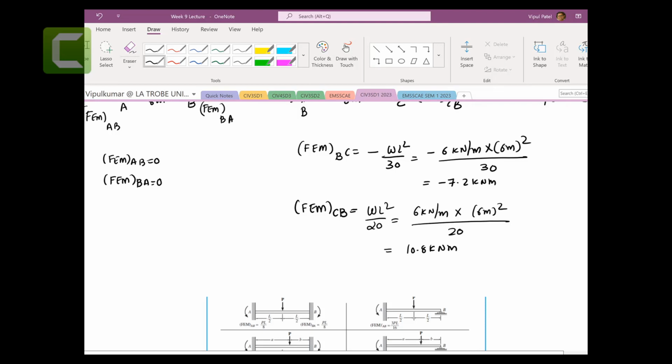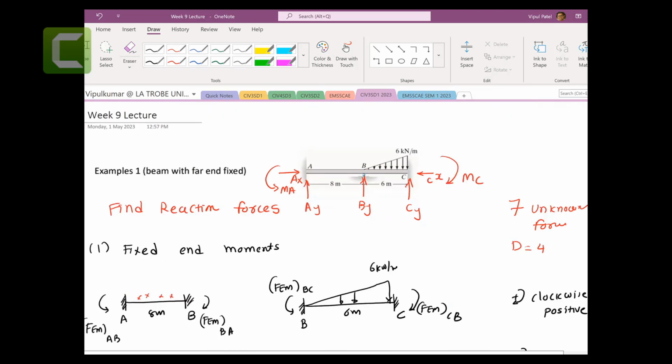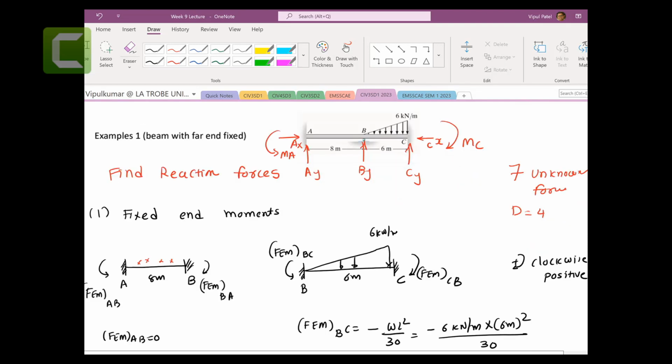Simple. So what you do, you take all your beams, break them down. Just break it. Take AB, make it all internal fixed and calculate the fixed end moments. That is step number 1. In all your displacement methods, you calculate the fixed end moment. Very simple. Tables will be given to you. From these tables, you identify the equivalent, identify the close match, and then you calculate the fixed end moment. So that is step number 1 that you always do.